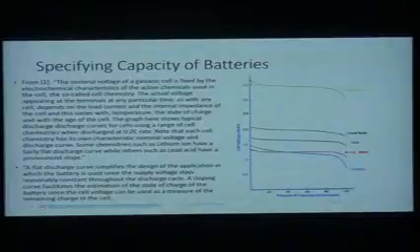The point of this curve is that, first of all, there are different levels of voltage, and that, if you think about it from an engineering standpoint, you have to match your voltages to whatever load you have, and certain loads will want to have particular voltages. So if the battery cell that you are using does not have the voltage you need, then you need to start thinking about stacking your battery so that you can produce enough of that voltage. Or same thing for supercapacitors, even more so for supercapacitors, as you'll see in a moment.